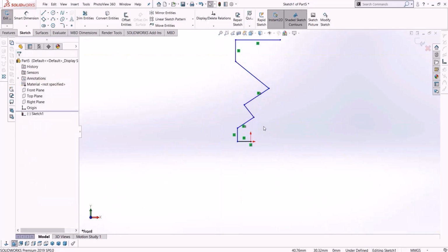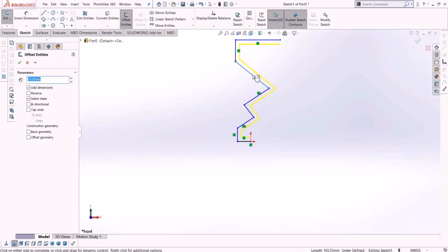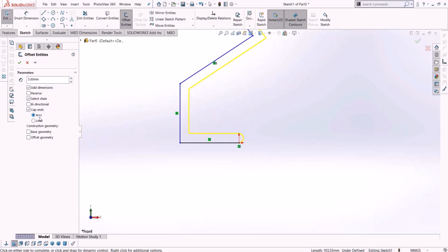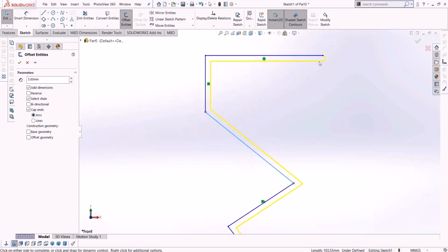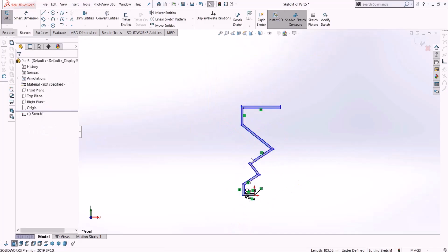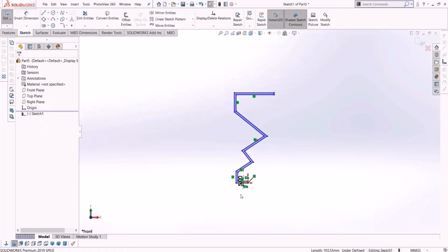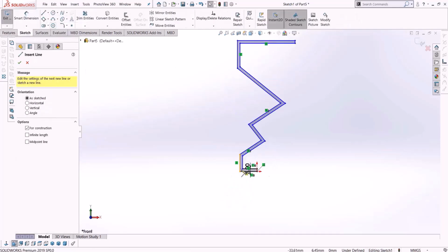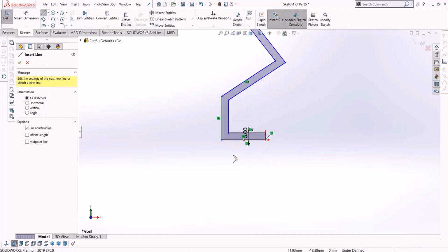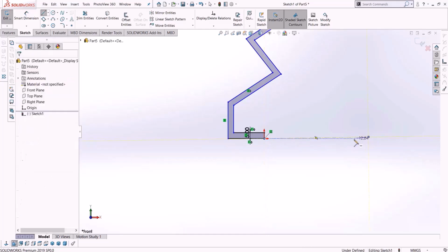For example, we have this shape, and I want to create an offset of approximately 5 millimeters from it. I want to close off the end. If it's in an arc shape, it will close in a manner that is curved, and if it's a line, a straight line will be sufficient for us. Don't forget that, of course. There is no need to draw the center line here because we have a straight line that will rotate around this. But since we have a defined state, we proceed.